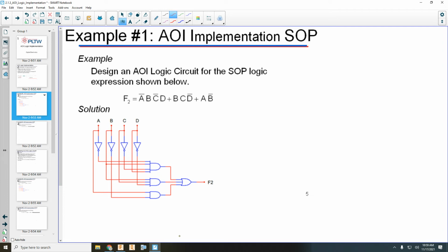The problem with that is it's going to come down to optimization, and also the fact, Carson, that there is no 3-input OR gate. It doesn't exist on a TTL chip. Okay, so what do you have to do? You got to cascade them together. And even if it did exist, let's do a little bit of how many parts would we need for this?